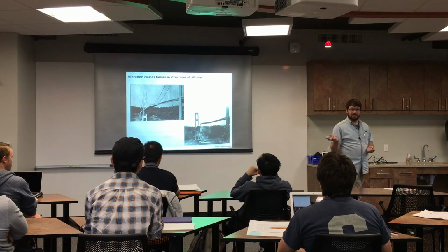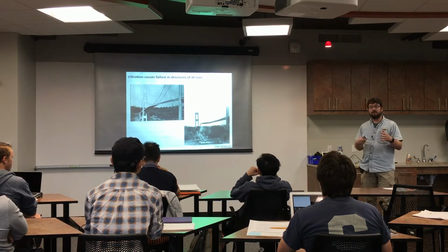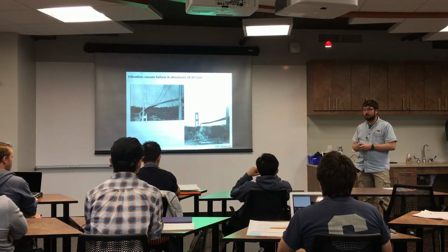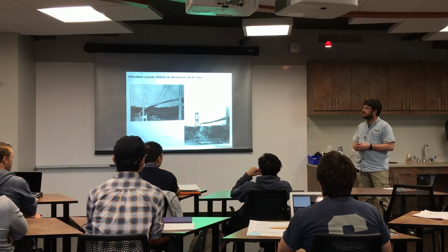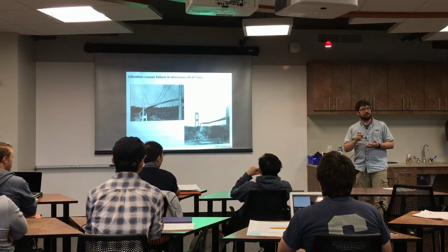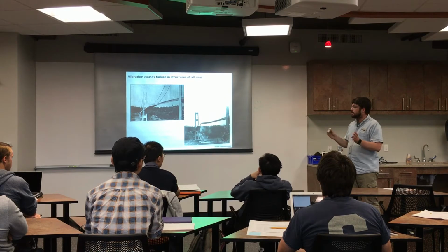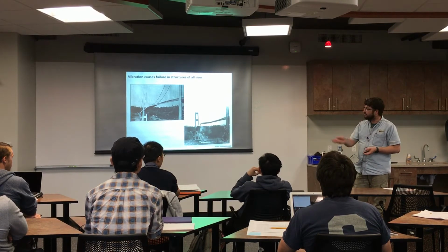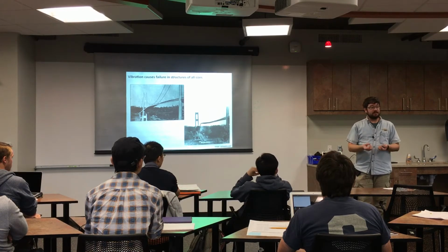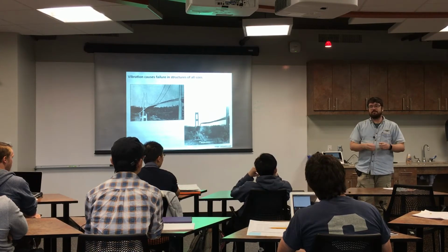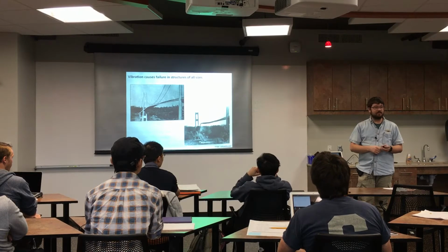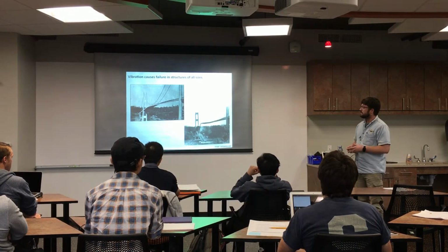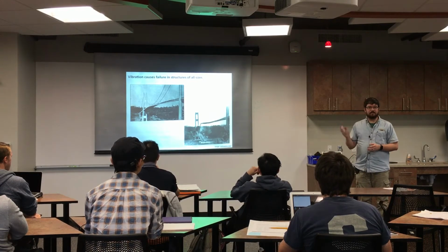It can also do this to machines. If you have something that's rotating rapidly, say a pump rotor or anything like that, that's a little bit out of balance and it's vibrating, it's going to wear the seals out, it's going to wear the bearings out, and it could cause catastrophic failure at some point. When you also have things moving in fluids like propellers, you can even get cavitation, where you get bubbles that form on the surface, and they can eat away at the propeller and eventually cause it to fail. So if you're dealing with things moving in fluids or rapidly rotating things, vibration is a big concern.